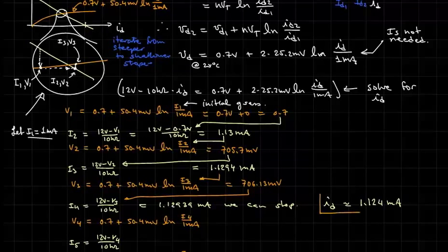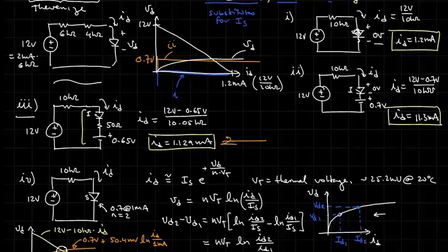So it turns out in this case that our ideal diode plus, or a constant slope diode right here of 0.65 plus 50 milliamps, actually predicted this current quite well. Yep. So you might wonder, well, how good is this model? Let's think about if we were to change the resistance or the voltage source.